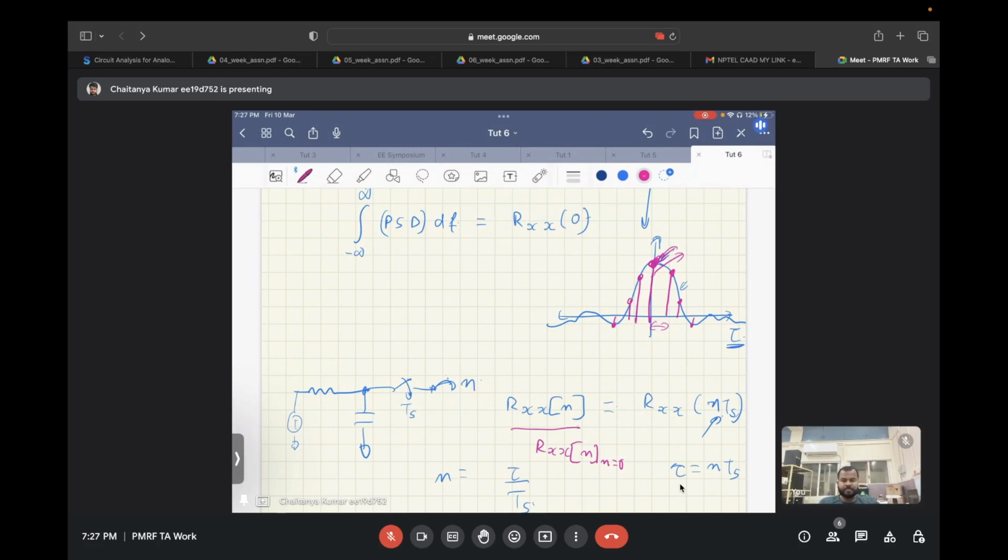So this is a mathematical way of showing that irrespective of sampling time, the total integrated noise power always remains the same. If you integrate in the digital frequency domain, from 0 to 2 pi, the power you get will always remain the same.